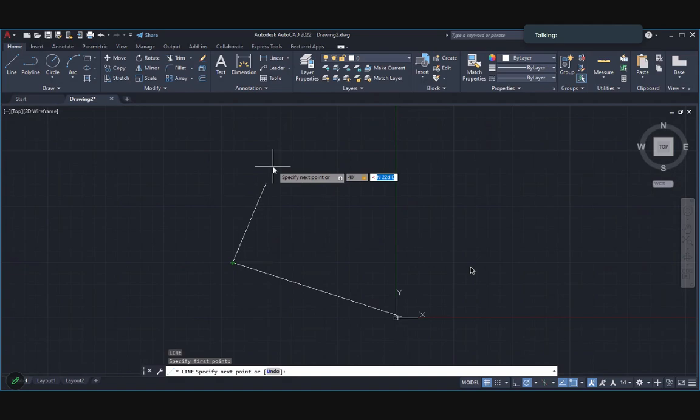So I backspace once, and I'm going to put in north 18, letter D for degrees, and then 30 minutes apostrophe, and then 0 seconds, 0 quotation, and then I'm going to put the letter E to indicate east direction, and I'm going to press enter, and then that's the second corner.